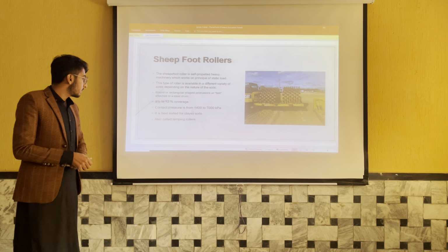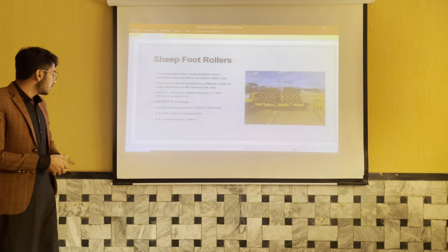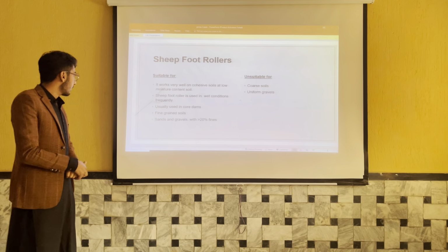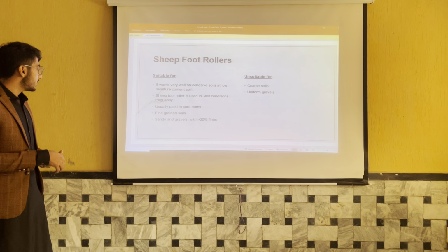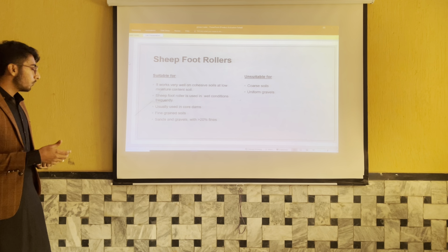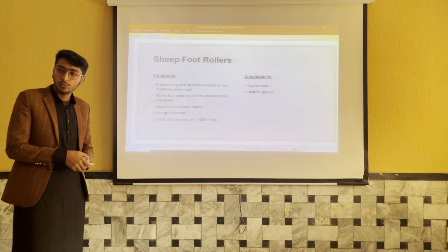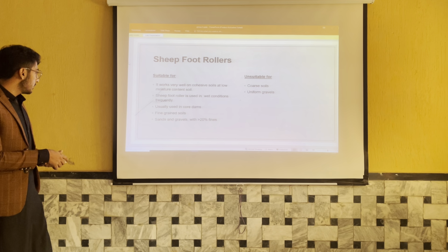Their contact pressure is 1400 to 7000 kilopascal. It is best suited for clay soils and is also called tamping rollers. It works very well on cohesive soils at low moisture content, and they are very good in wet conditions. They do not work well in fine grained and dry soils. Usually used in core dams.